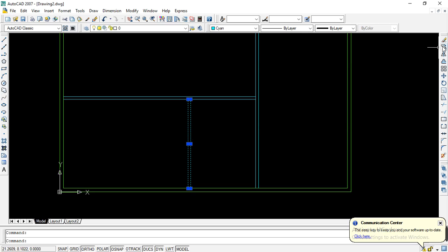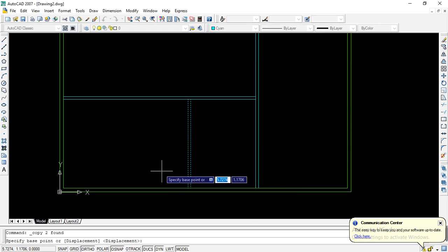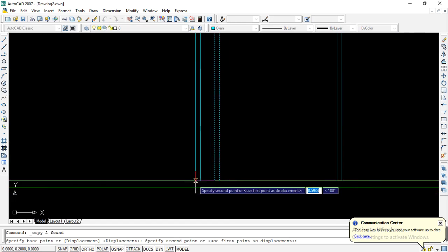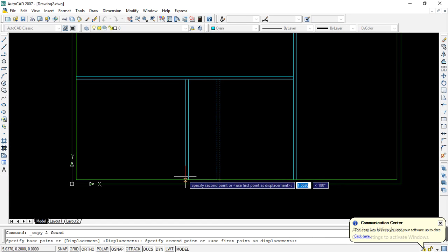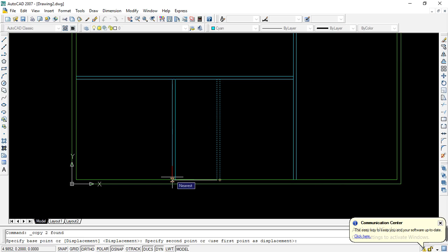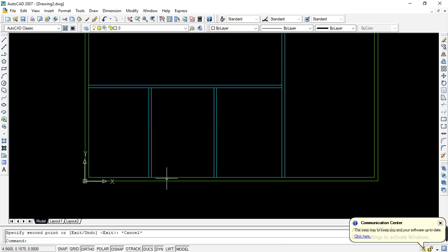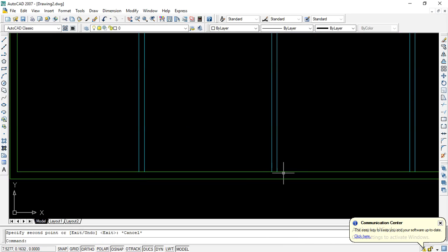Good. So now what I'm doing next is selecting this object, and then after that I gotta duplicate it. Okay, so using the copy symbol, then it says I'm pressing the base point of the object, and I'm going horizontally to the left. So how much dimension? So here 3.65, and escape. Good. So now I'm gonna trim those lines off.